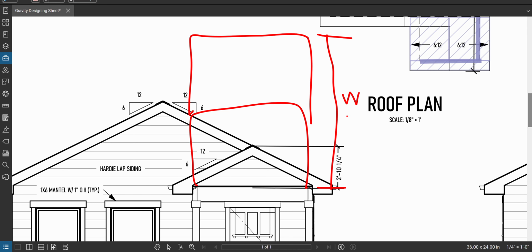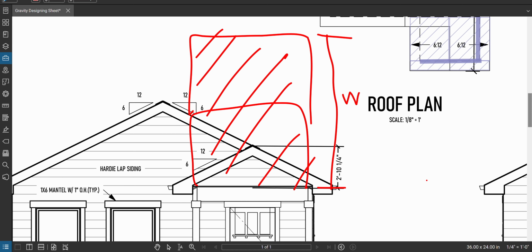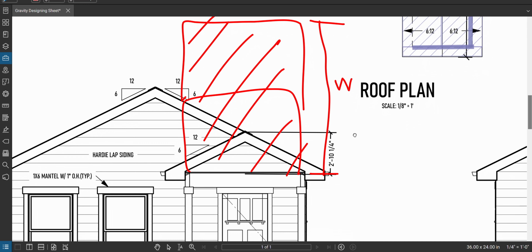It's my tributary width because it's trying to get a load area, right? This is my loading area. It's going to take the pounds per square foot number that I say the wall weighs. It's going to take that width and multiply it by it, and it's going to apply that in pounds per linear foot to the whole length of my beam because it's, well, in this case, a tapered load, but if this case was flat, it'd be uniform. So that's what I'm doing here. We're going to use the tributary width rule in order to establish the height of the wall.